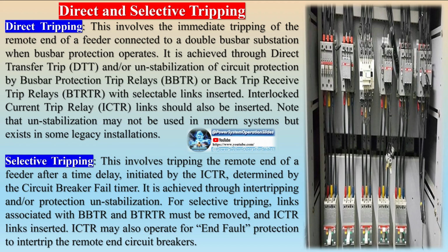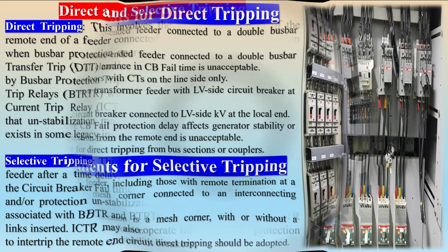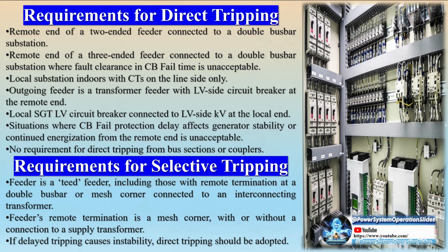An advanced differential relay can use a directional element to provide extra security during an external fault with CT saturation. During such events, fault current contributions flow through each non-faulted terminal and aggregate in the faulted terminal, causing the CT on the faulted terminal to saturate and produce a false operating current. However, the current in the faulted terminal will be out of phase with the other zone currents, indicating an external